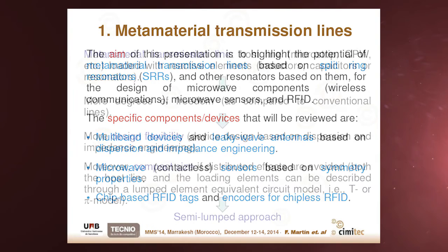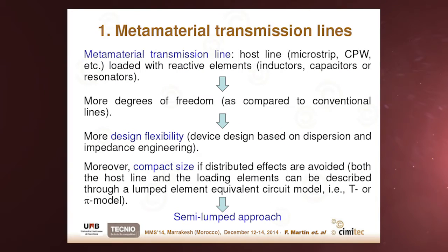Well, what are metamaterial transmission lines? Christoph talked about metamaterial transmission lines before a little bit. Let's go again to the detail of these lines. Essentially, a metamaterial transmission line is a host line, microstrip, CPW, etc., loaded with reactive elements, inductors, capacitors, or a combination of them.